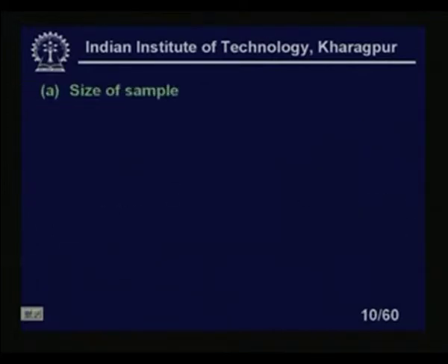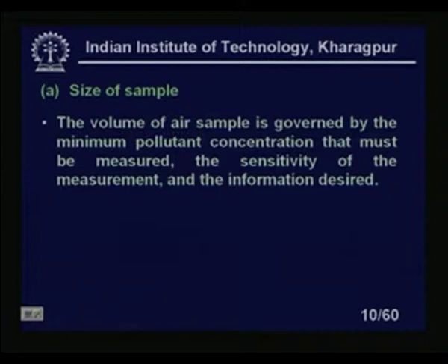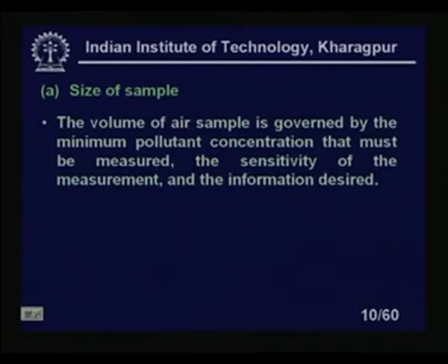Size of the sample. The volume of the sample, I am not talking of the size of the dust particles, but the size of the sample, how much air you will collect from the environment to analyze it, right. That is, I am talking of the size of the sample. The volume of air sample is governed by the minimum pollutant concentration that must be measured, the sensitivity of the measurements, and the information desired.